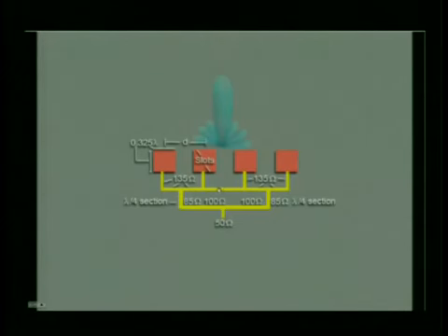This feed network is made of transmission lines. These are microstrip transmission lines for this particular example. As you know, length and width control the L and C. So, the L and C is controlled by this. Based on this, a matching condition is generated. So, R plus jX, the X is controlled, and accordingly you get an impedance. That impedance is matched with the patch, and you are feeding the patch in this location.